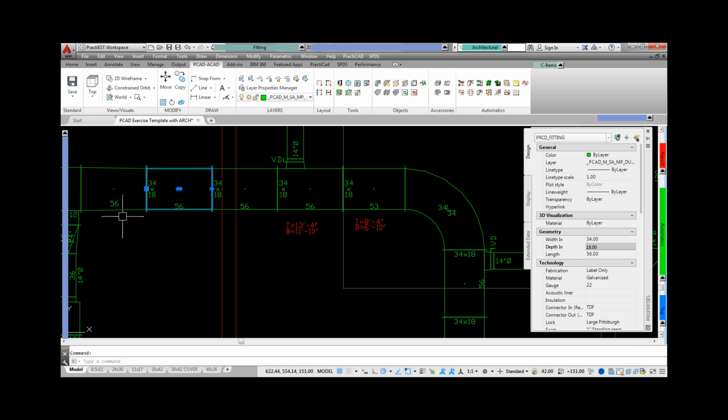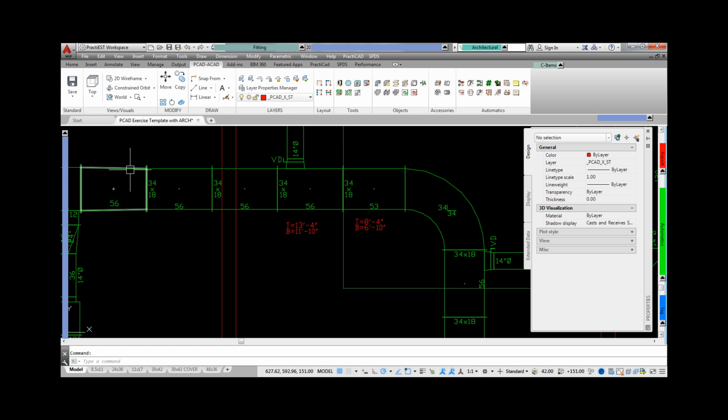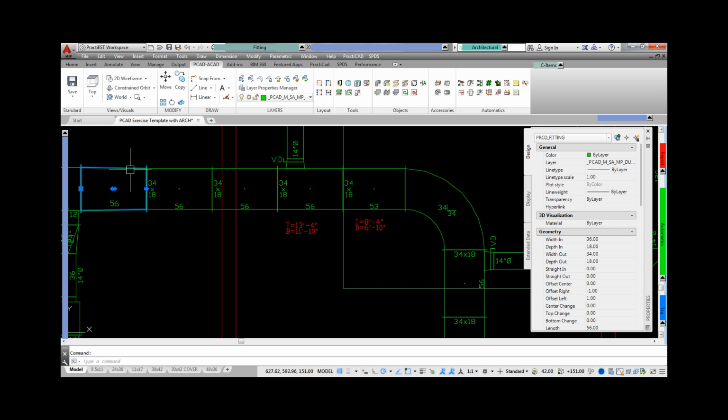Notice the depth in and out are equal, and notice there is no top-up-down tag. This is because the user did not want one, there was no change in depth. However, edit the fitting and changes, and you can see it immediately puts the proper top-down tag in place. It is also changing the relative elevations for each tag from its particular reference point, all the way downstream.